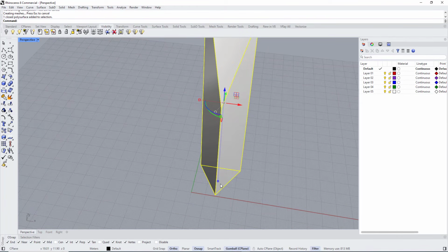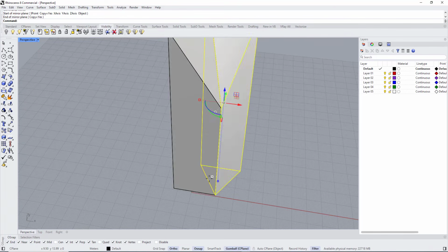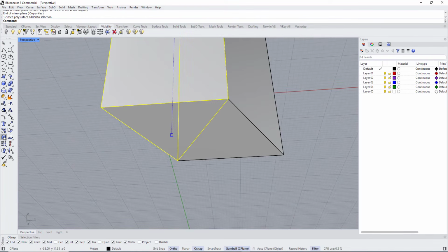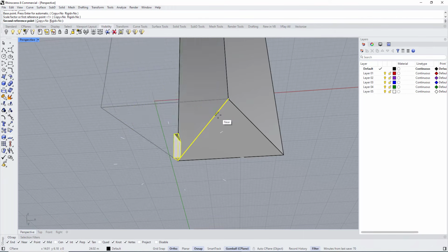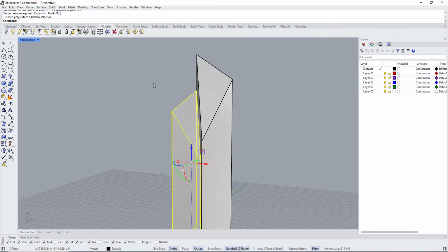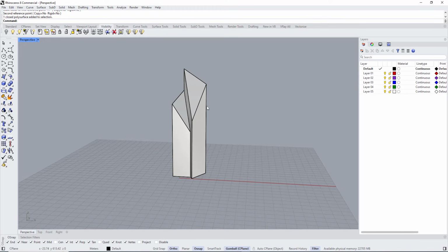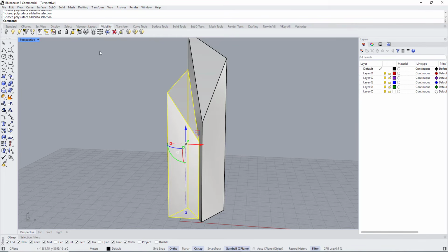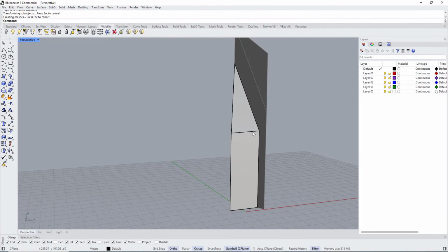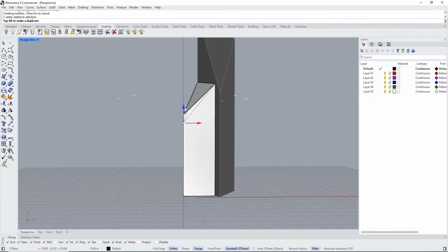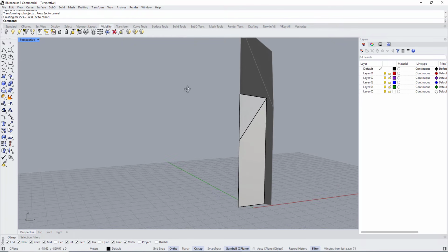Now if there are two towers together, I maybe come here and type mirror to mirror it in this direction. Maybe start scaling it a little bit, choose scale 3D, scaling it maybe 24 meters. And now I want to modify this without selecting this one by accident. So I select this one and in the visibility choose isolate. So now I can select this one and start Ctrl Shift and start modifying the vertex. Maybe something like this. And so on.